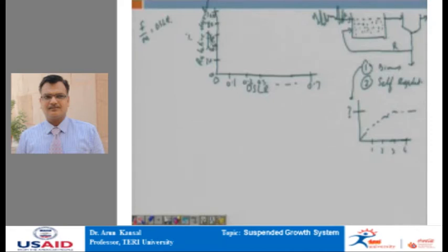Here, the organic sludge loading rate or food to microorganism ratio is nothing but soluble BOD divided by kg of bacterial mass. If I draw the analogy which we had done previously, for a given level of food, if we have a large number of organisms, the food will be consumed very fast.